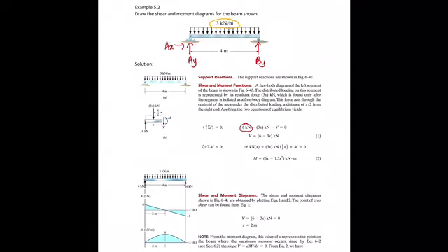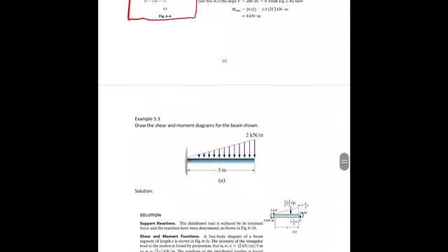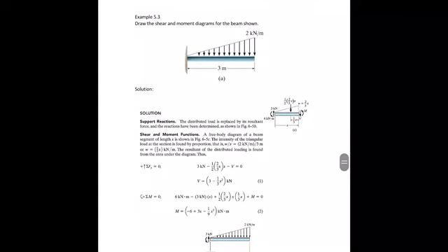and 3x is how you solve the UDL. From moment, you know that moment is equal to force times distance. So this is the force and this is the distance. Force and distance, then you get this moment equation. Then you can plot the shear and moment diagram. Please study how they get this diagram. Okay, same goes to the next example. So you can read the solutions.